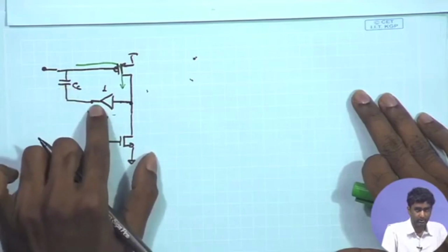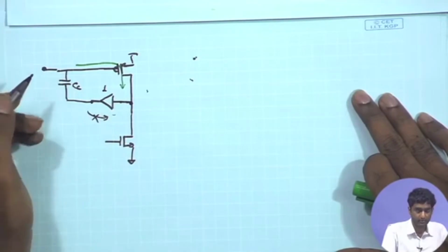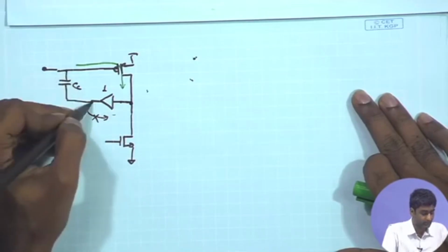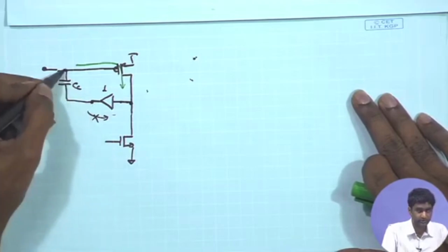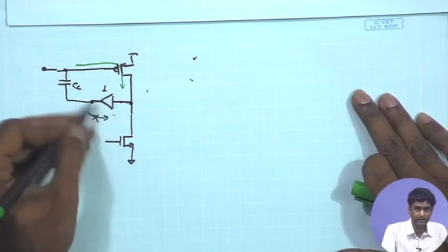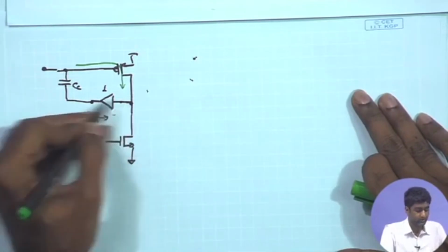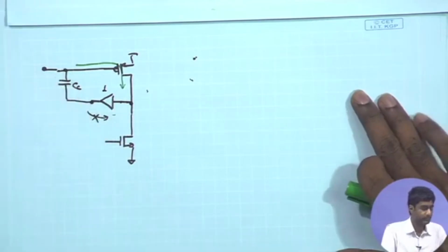Now, does it still have the Miller effect coming into picture? Yes, because the gain is remaining the same. All you need for the Miller effect and the Miller compensation is that the gain within the signal or voltage level at the other end of the capacitor with respect to the first end should be sufficiently high, and that is not changing much because of this unity gain amplifier, because the gain from the output to this point is 1, therefore, the Miller effect remains intact.